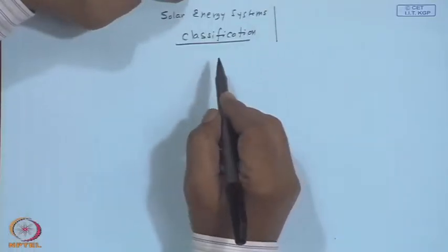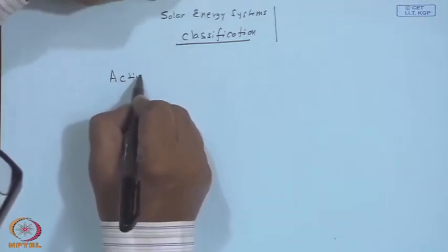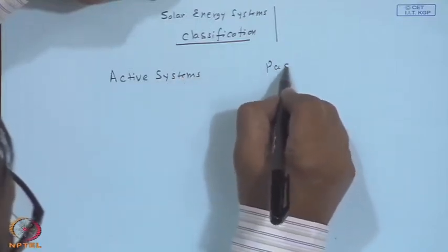Practically, we are in a position to calculate the solar radiation on any tilted surface or tracking surface, and then solar collectors, flat plate or concentrating, we have collected enough detail, so that we can have a performance equation from which you can calculate the output from a solar collector for given input conditions like solar radiation, flow rate, etc. However, we have two major types, which we call the active systems and then passive systems.